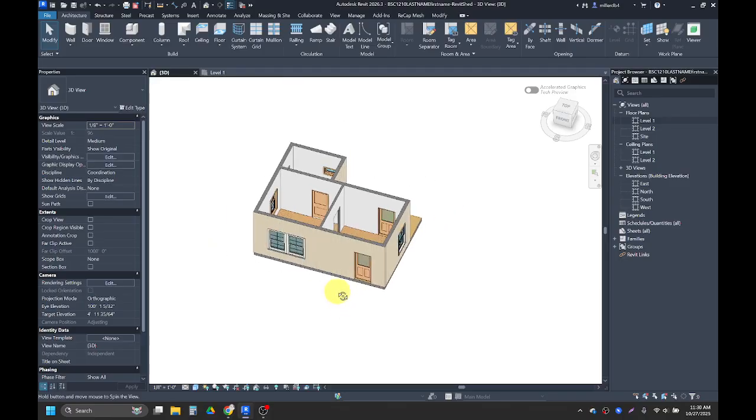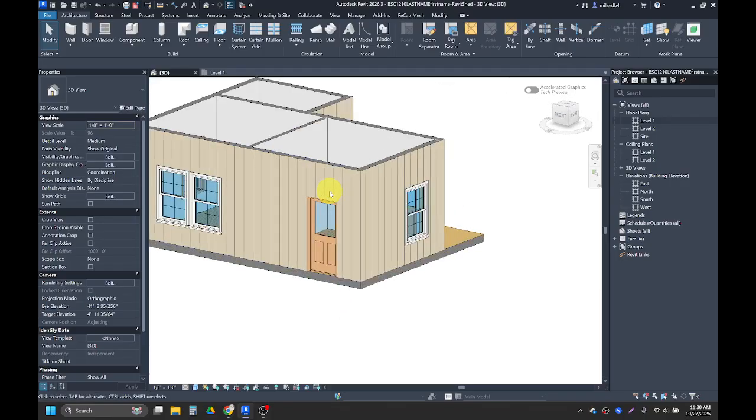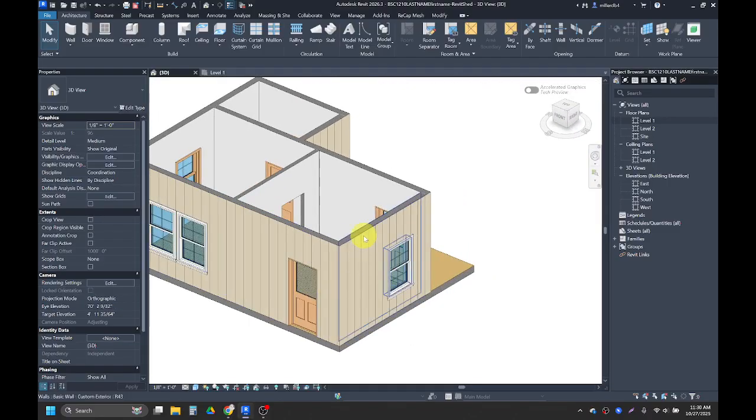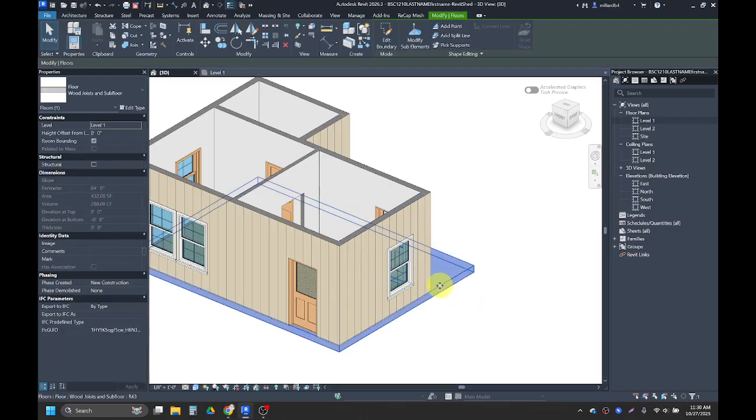One problem that arises when we create our floor is that our exterior walls almost seem like the finish is floating above them. So what I want to do is adjust my exterior walls so that they are lower and they're going to cover this floor. So this floor here is 8 inches thick total, which means I want to bring these walls down 8 inches.